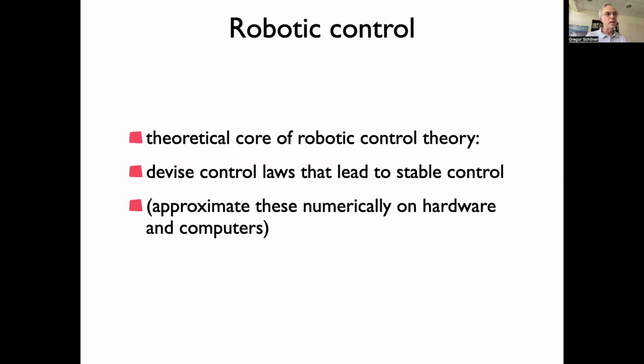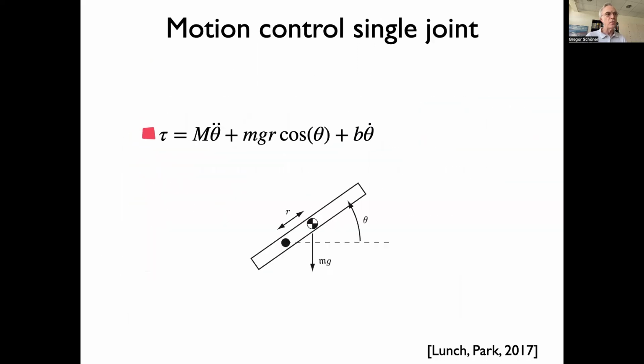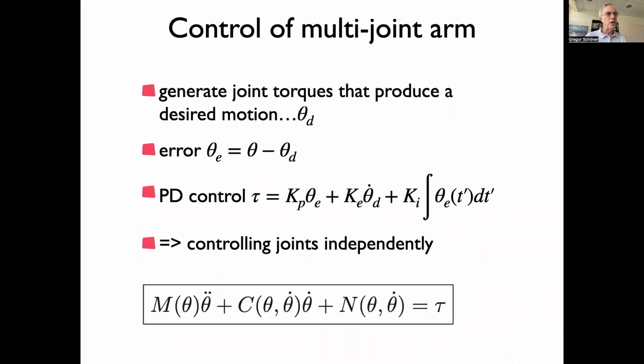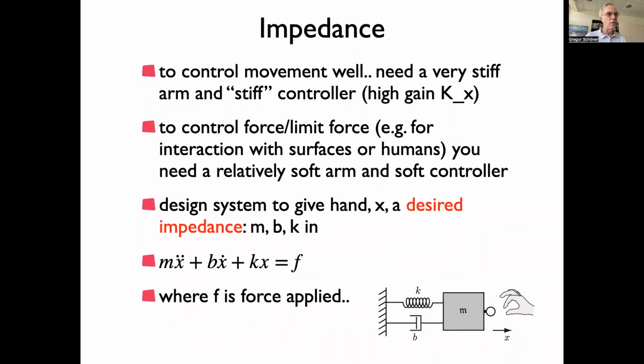And the other major difference is that humans are always doing compliant control. That is, when we're interacting, and we're very good at interacting with the world, we're always interacting by determining how stiff and viscous we are with respect to that world. You may have an intuitive sense of this: if you take a fragile object and you try to screw something on that object, you determine exactly how stiff you make that arrangement.